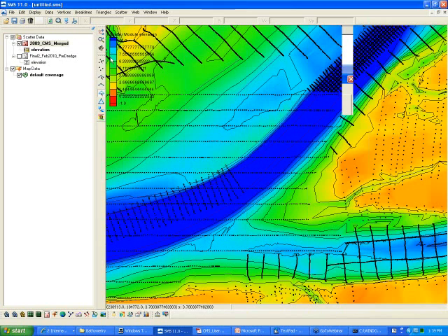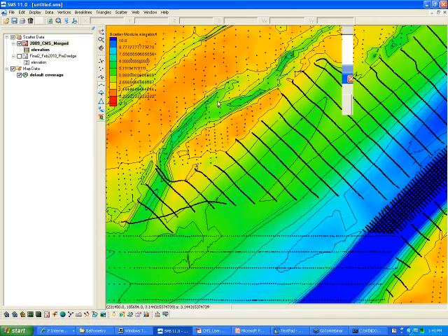Okay. The way you insert break lines, and you covered that last week, is you have this tool here, which is create scattered break line. And you click on points, create lines. And the break lines will force the triangulations to not cross those lines. And this is really useful for controlling the interpolations and the orientations of those surfaces between the triangles. It makes a really, really big difference.